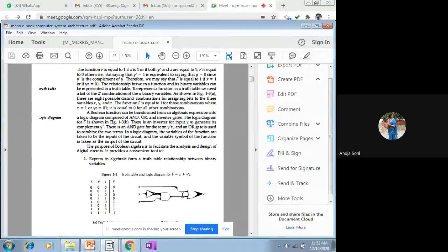If we have two versions of the logic circuit diagram, one complex and the other the corresponding simplified version, the functionality of both will be the same. They will generate the same output for the various combinations of the input. The only difference is that the simplified version requires fewer logic gates.